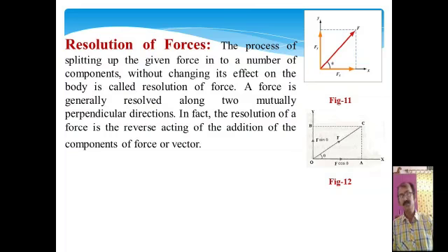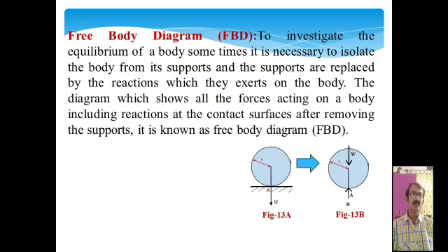Now free body diagram, which is simply written as FBD. To investigate the equilibrium of a body, sometimes it is necessary to isolate the body from its support, and the supports are replaced by the reactions which they exert on the body. The diagram which shows all the forces acting on a body, including the reactions at the contact surfaces after removing their support, is known as a free body diagram.